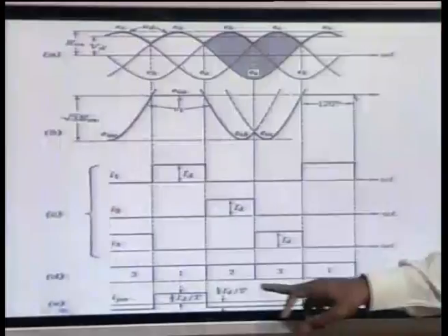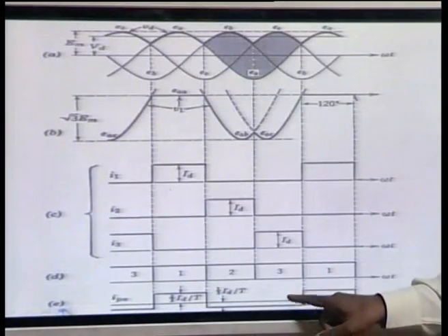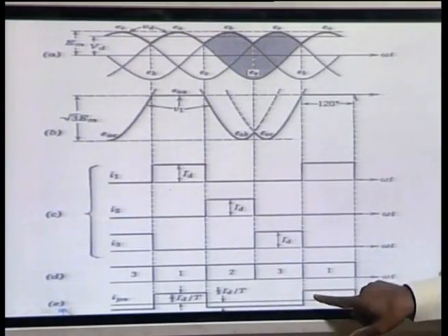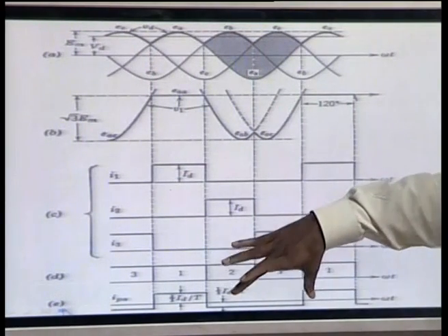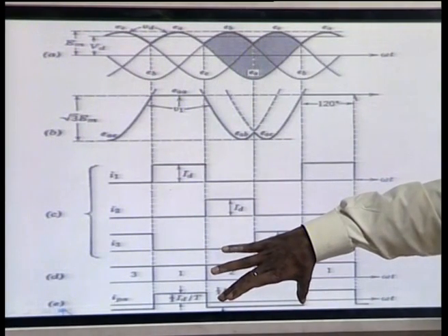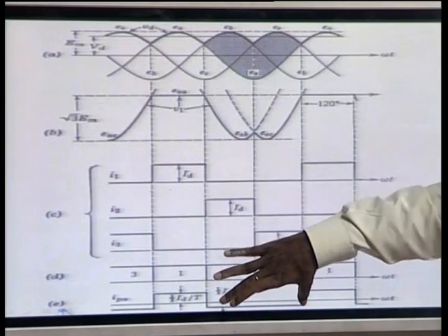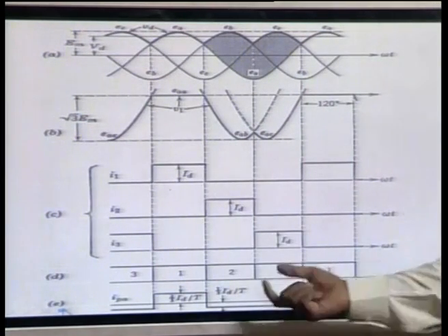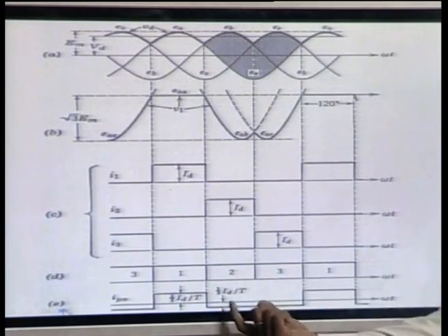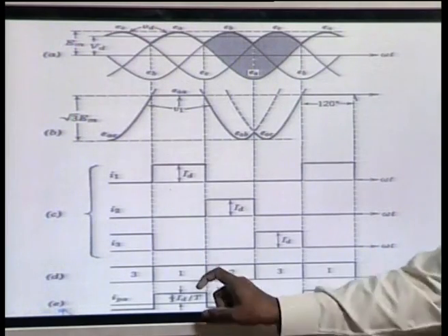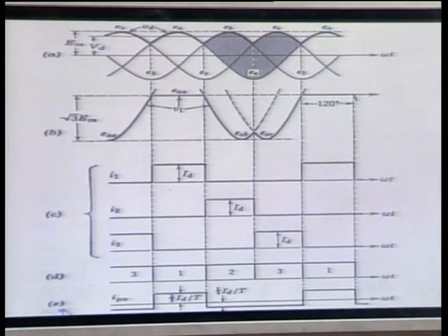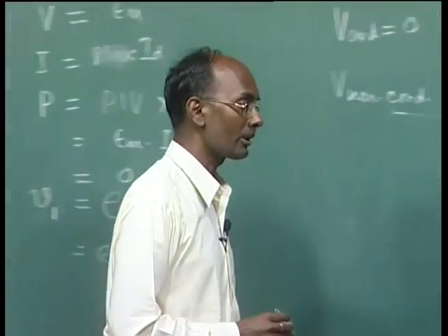But in this case, if we take the average here, the DC is average 0, but this phase, for this period, has less magnitude but conducts for a longer duration, meaning 240, 120 and 120 degrees. Here it is taking more current for this. So, your transformer is not symmetrically loaded, I can say, and that is why proper care should be taken for this.